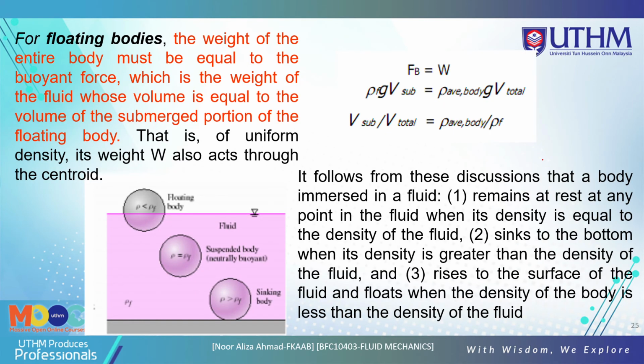principle. Now we look at the concept for floating bodies. For floating bodies, the weight of the entire body must be equal to the buoyant force, which is the weight of the fluid whose volume is equal to the volume of the submerged portion of the floating body. For a body that is of uniform density, its weight W also acts through the centroid. So we use this equation.